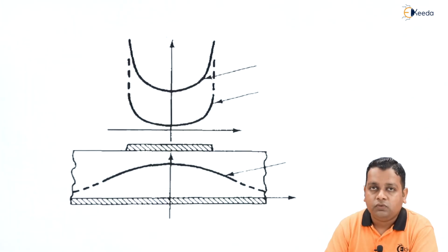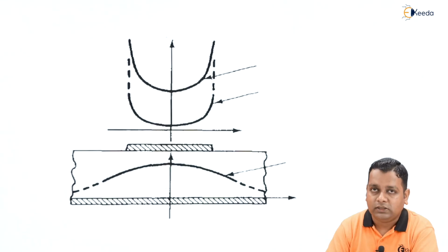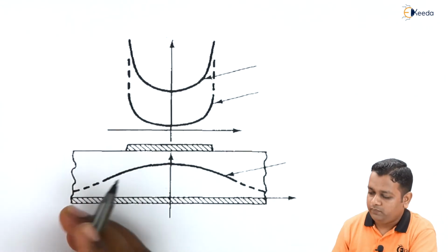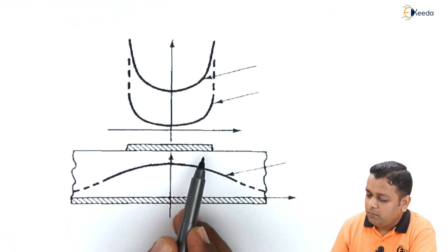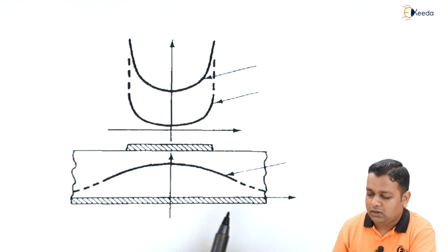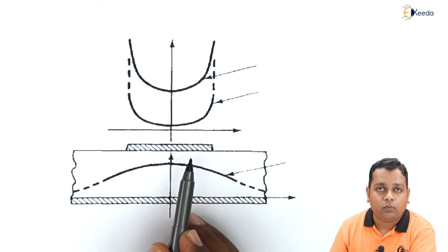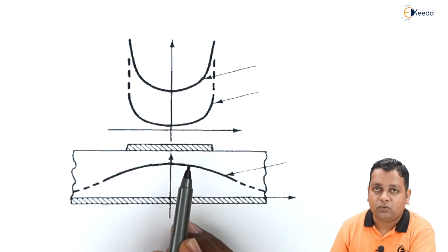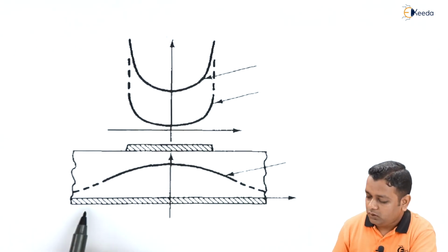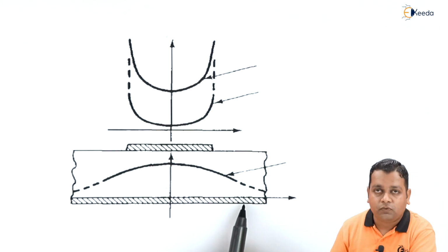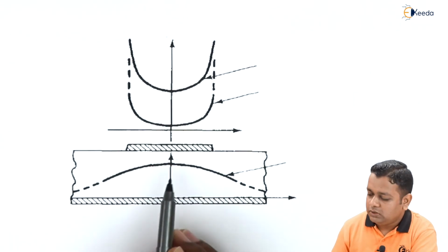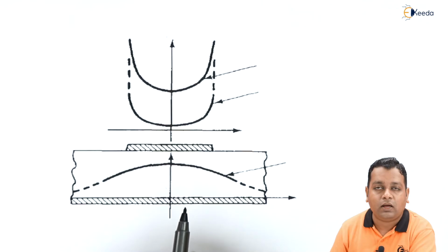With respect to the conductivities and the current densities, we have a schematic diagram where we have represented the structure of the microstrip line. This is the strip conductor, which is at more positive potential, carrying the microwave information, whereas the other shaded portion is the ground plane, separated by the dielectric material.